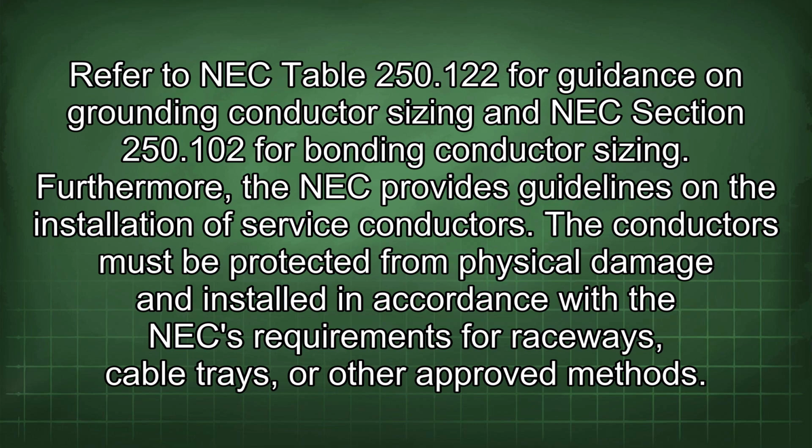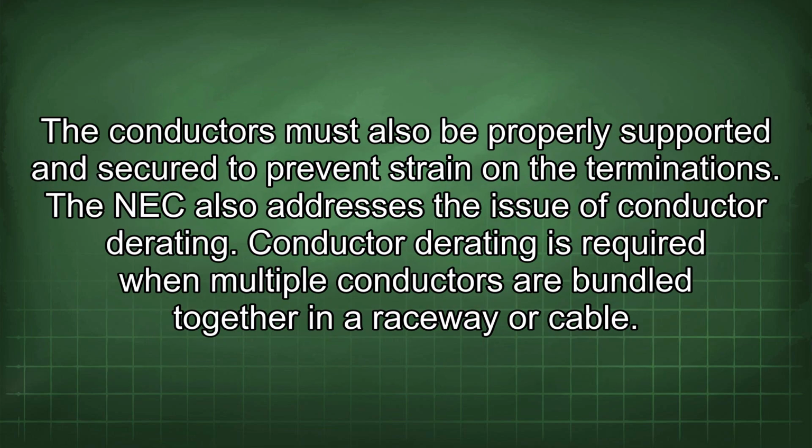Furthermore, the NEC provides guidelines on the installation of service conductors. The conductors must be protected from physical damage and installed in accordance with the NEC requirements for raceways, cable trays, or other approved methods. The conductors must also be properly supported and secured to prevent strain on the terminations.